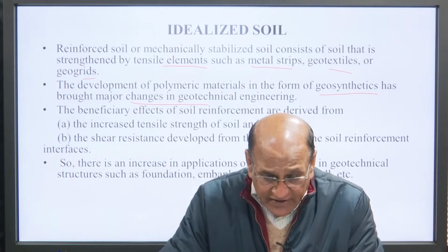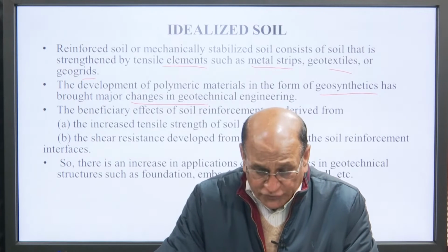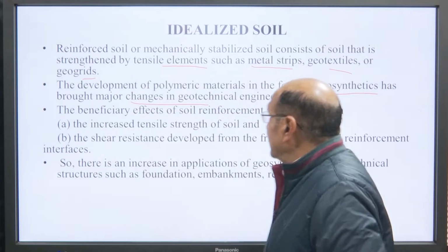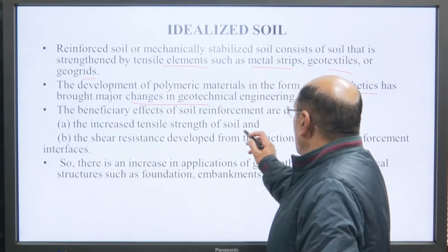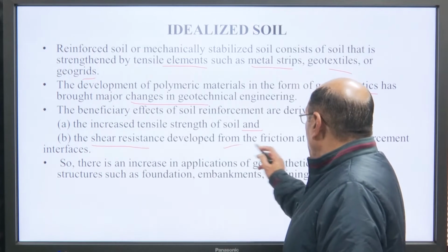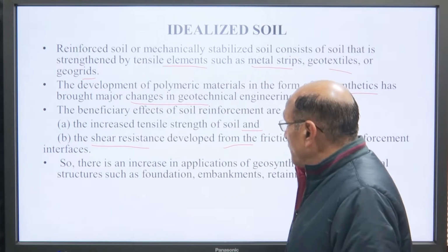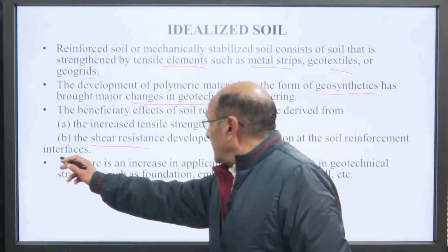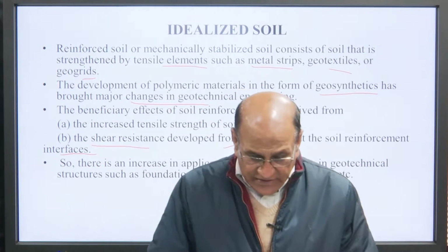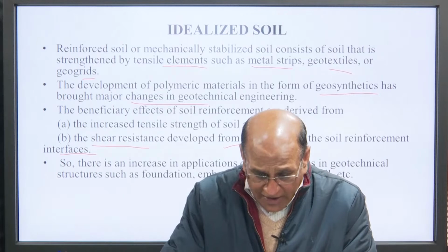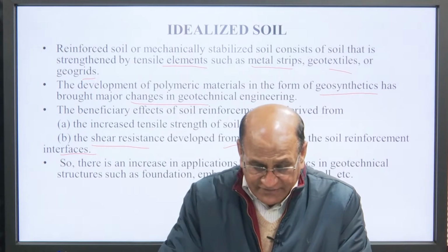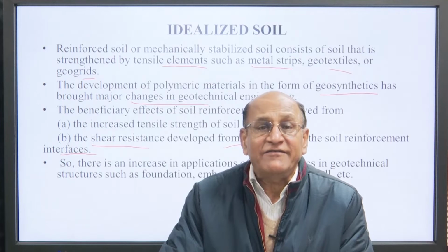The beneficial effects of soil reinforcement are derived from, first, the increase in the tensile strength of the soil. Second, the shear resistance developed from the friction at the soil reinforcement interfaces. So, there is an increase in application of geosynthetics in geotechnical structures such as foundations, embankments, retaining walls, etc.